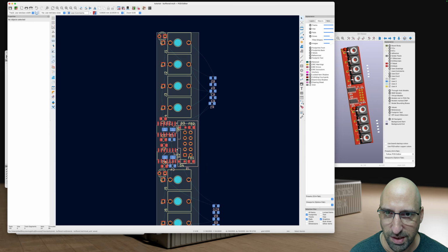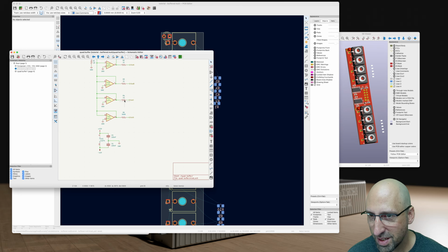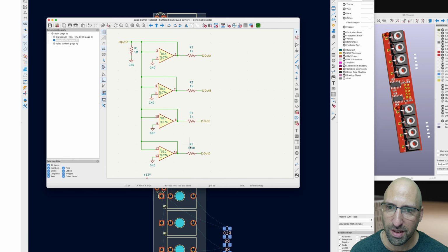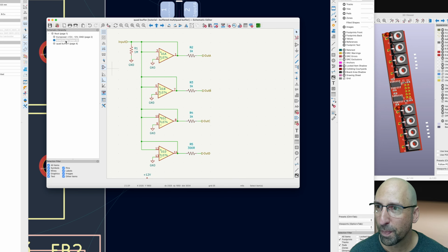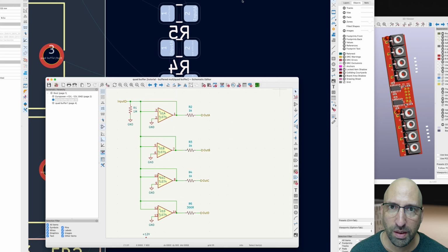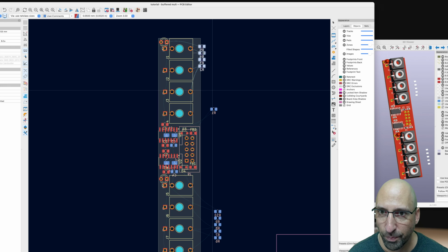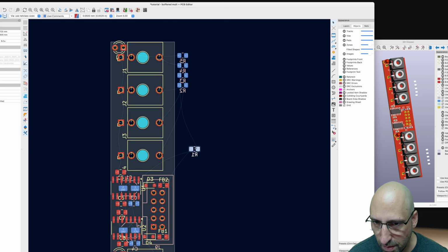So let's have a look at these. I'm guessing, remember if we look on the schematic, remember these resistors that we moved into the little buffer sub-circuit. That's what those 4 resistors are all about. So if I grab all of those, this is for buffer channel A, and I come back here. So these ones are going to be over here, and they are essentially for the LED, and there's probably this one as well. Yeah.